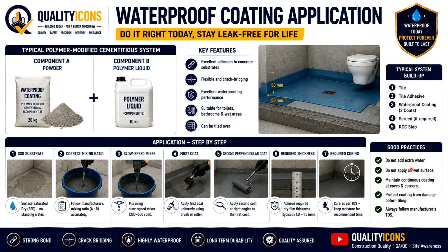Good practices are: don't add extra water, don't apply on a wet surface, maintain continuous coating at coves and corners, protect the coating from damage before tiling, and always follow the manufacturer's TDS.